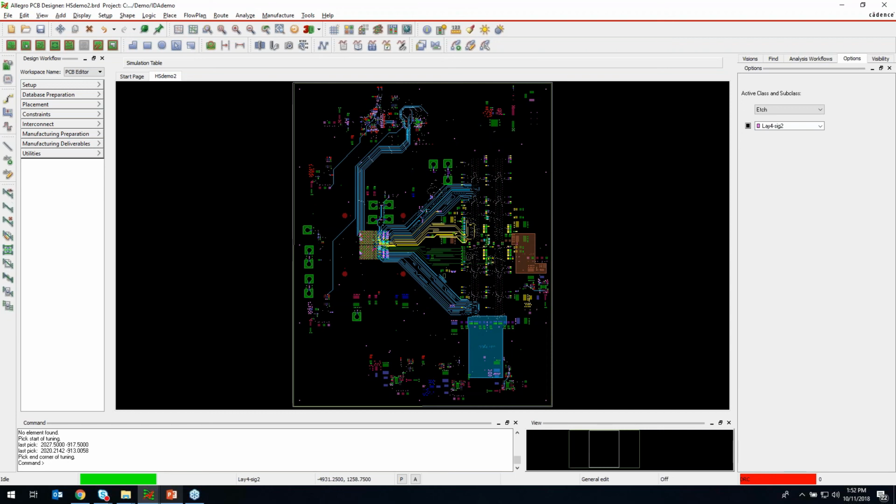First question I have for you, Jerry, is can coupling vision identify coupling in the z-axis, for example, two nets on different layers? Yes, that's just about what it focuses on, is layer-to-layer coupling. That switching that I mentioned there, where you can actually have it detect coplanar coupling and coplanar impedance, takes care of the coplanar in addition to the z-axis coupling. So yeah, by default, it's essentially layer-to-layer coupling involved.